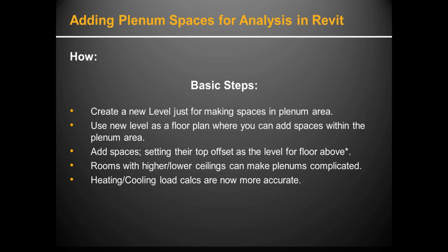We'll set their top offset, which is the maximum top offset. If it doesn't hit any bounding elements, it will stop when it hits whatever we specify, typically the floor above.